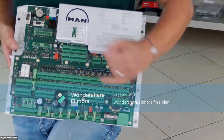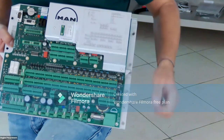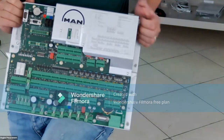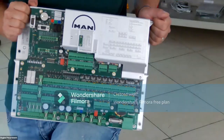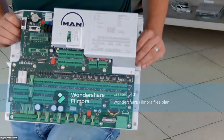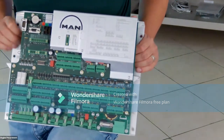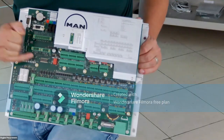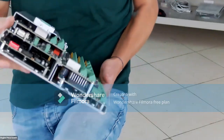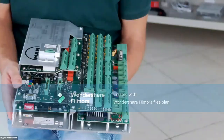On the front side, we have the S1 DIP switches, this one. For normal operation, all of these S1 DIP switches must be in the off condition. So this is a new MPC from MAN. I removed the package, the plastic bag and whatever else it was packed in. And before installing, I make this check. The S1 DIP switches, all of them must be off. The side DIP switches, number 1 and number 8 in the off condition.